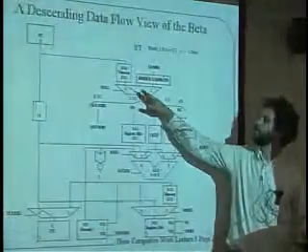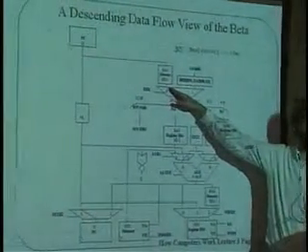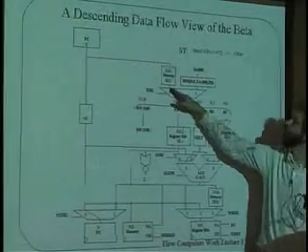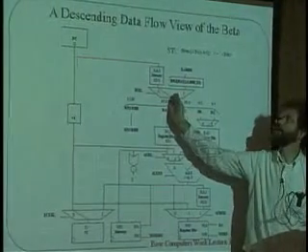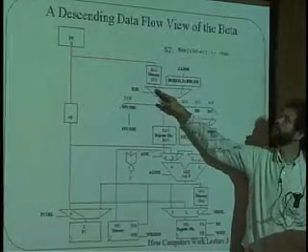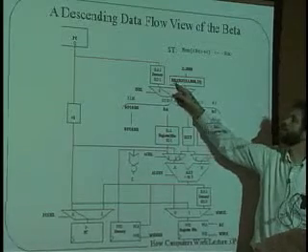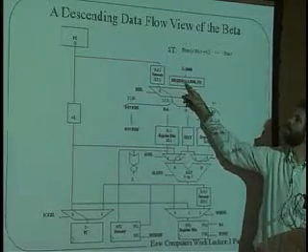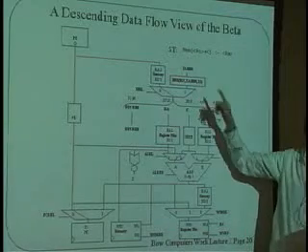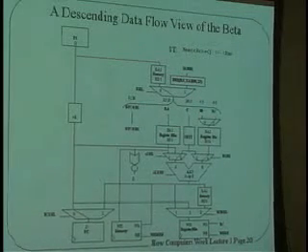Now there's one that I'm not going to talk about during the lecture today because the last few classes have taken too long, I think, and that's going to be what are called exceptions. In certain cases, we're going to actually want to take this multiplexer right here and shift it over to the right. What that's going to do is not do an instruction that we want to do. Instead, it will substitute in an instruction saying branch if 0, R31, XADDR, comma, XP. Remember, XP was that exception pointer register I pointed out in the last class.